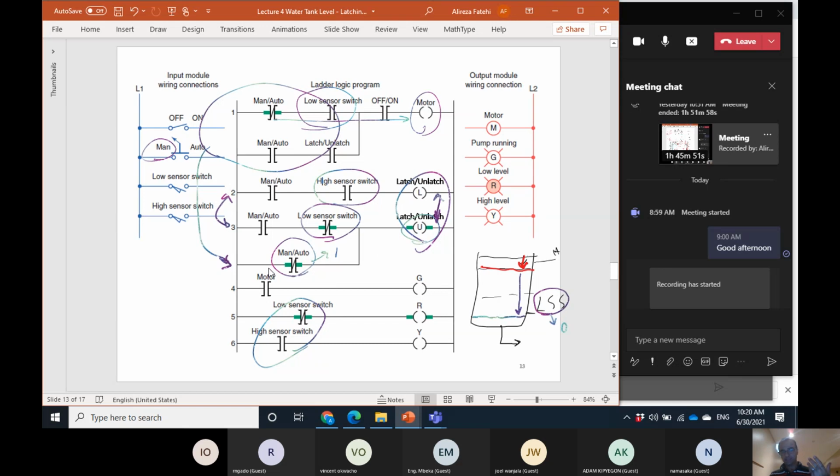In fact, by this branch, we stop the motor, or let's say unlatch the command on the motor that was generated from the auto mode, and leave everything to the manual control philosophy to decide whether to turn on or off. It is just because of that, but most probably we don't need this. This is just redundant.